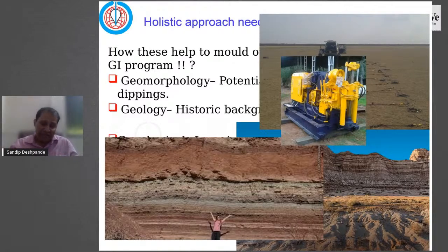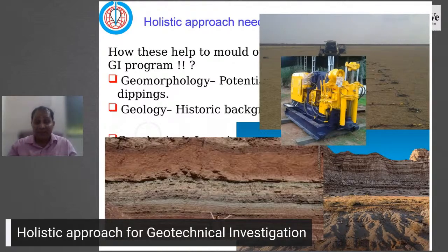Moreover, the geophysical investigations or the geology, the other 3Gs, what I am proposing, would help us quantify our geotechnical investigations, the number of boreholes you need for a specific site. Yes, I need more boreholes here. Yes, I need fewer boreholes here. Yes, the stratification is quite uniform and consistent in my geophysical model, so I can reduce the intensity of geotechnical investigation. So this kind of leveraging can be done based on available knowledge and information if all the 3 other Gs are explored.